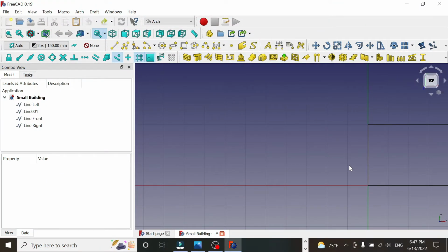Okay, let's create our new box using polyline, multiple points line. So here are all zeros point. We're going to build our new box over here with this start point. Let's calculate the numbers of this start point. If this is 0, going left in X gives me negative numbers.